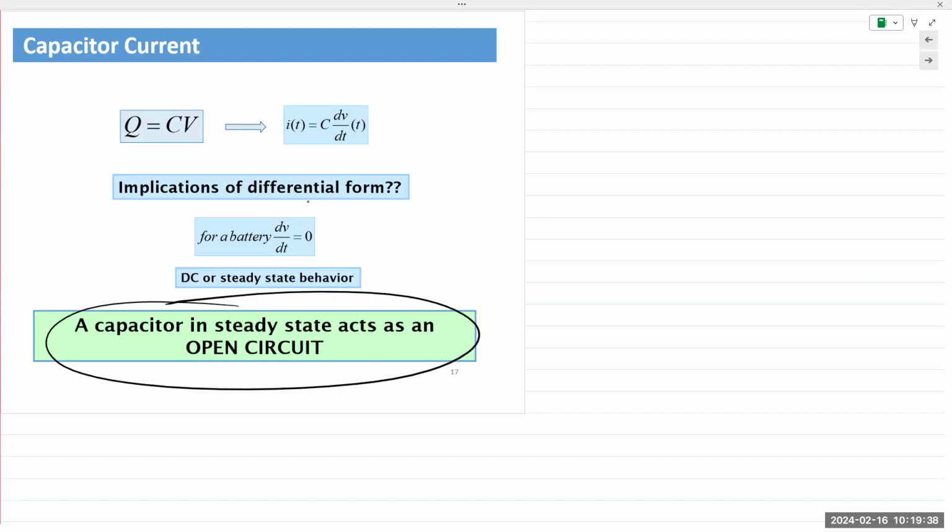Just on a tangent, the inductors we have in the EE department are both of high quality as well as of low quality. The ones that we use for these labs are of low quality. That's on purpose, to show you that an ideal inductor, or a really good quality inductor, should not have any voltage across it. But because these are low quality inductors, they have some DC resistance. And when you have a DC resistance in there, some of the voltage is dropped across that inductor.